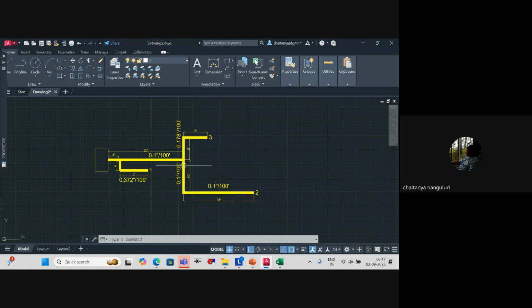Okay. So this is clear. Now when we design it like this, we will make sure that the airflow rate is constant through the system. That means from the AHU to 1 to 3, you have maintained the same friction, which is 0.45, which will definitely result in equivalent airflow. Now, whatever air I throw, if I throw 500 CFM, it will divide it by 3 equally. If I throw 3000 also, 1000 CFM will equally flow through each and every terminal.